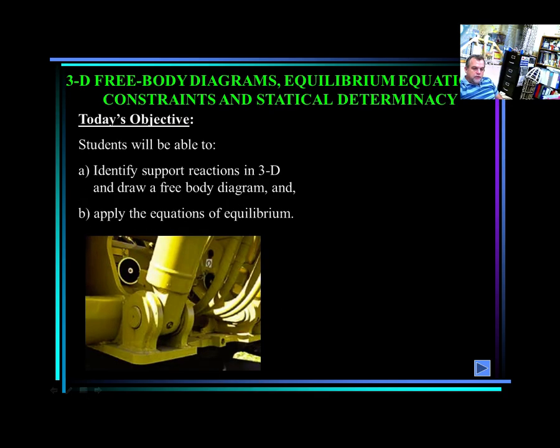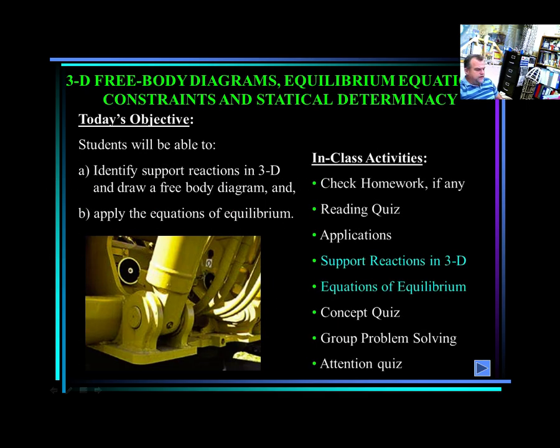So today we're going to be working with 3D equilibrium. And I used to spend some time here on this type of supports. It's the same thing. What is the difference between 3D and 2D? The difference is 1D. So basically, what this implies for 3D equilibrium is that if you have an element like this rigid body, that rigid body is going to be able to move in this way, in this way, and in this way. So you have 3 possibilities for translation. But at the same time, it can also rotate in this way, or in this way. So you have 3 different rotations. The total number of equations is 6: summation of forces in X, Y, and Z, and summation of moments in X, Y, and Z, respectively.